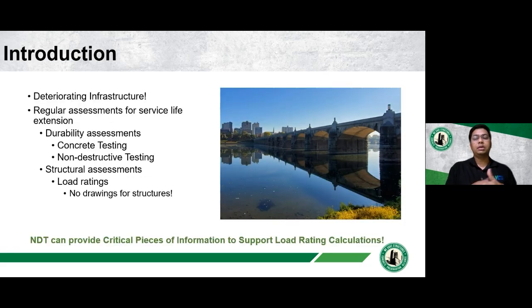So to begin with, the safety of bridges is a critical concern for the transportation industry, as we all know. With deteriorating infrastructure, regular assessment becomes imperative for estimating or extending the service life of the structure. These assessments could either be durability focused, which may include some concrete testing in addition to some non-destructive testing, or they could be structural in nature, where the primary focus would be load rating calculations.